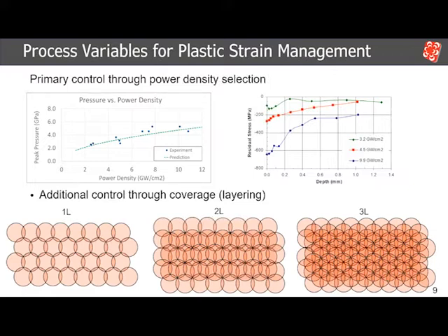The processes work similarly, and it's just how the actual material responds to the process. We can control our intensity through selection of power density. As we increase power density, we get a bigger bang in our material. Shown on the right side of the screen is how our power density influences residual stress. Similar characteristics are developed as a function of forming.